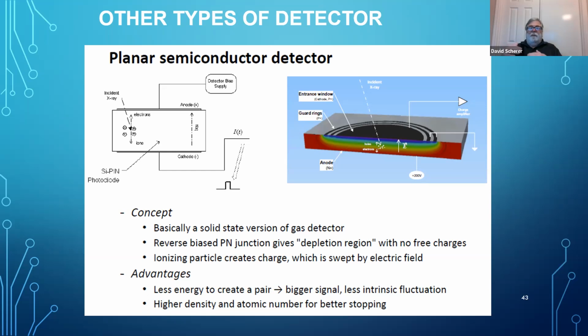And then there are bands where the electrons cannot have certain energies. So when a photon or any radiation causes ionization, the electron is moved into a conduction band where it can move around through the solid. The hole that is left behind is limited and can't move as rapidly. This process allows us to collect a charge that's proportional to the radiation that caused the incident ionization.